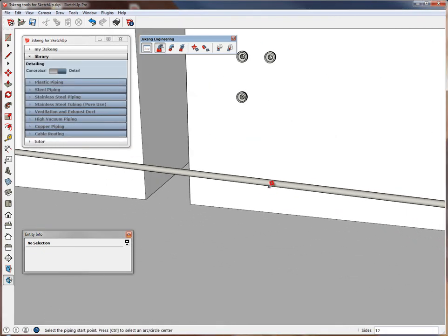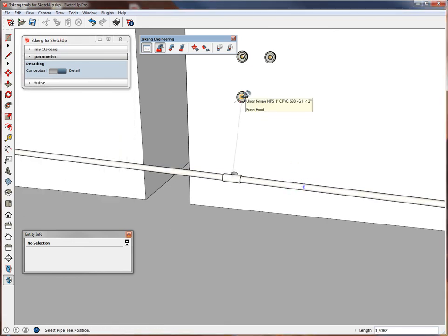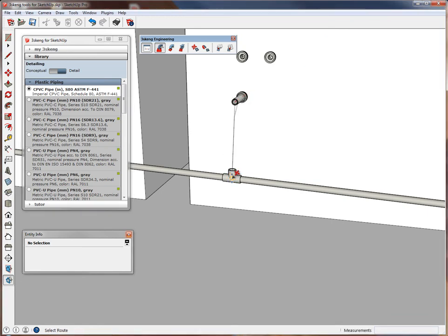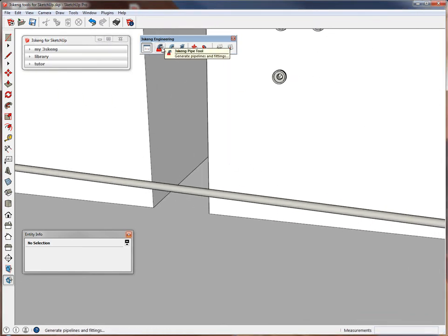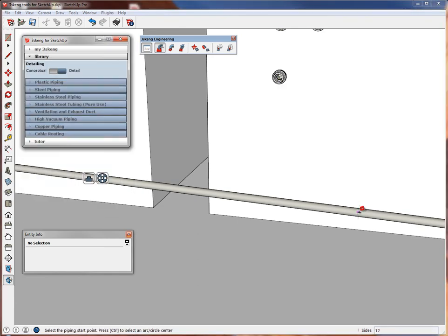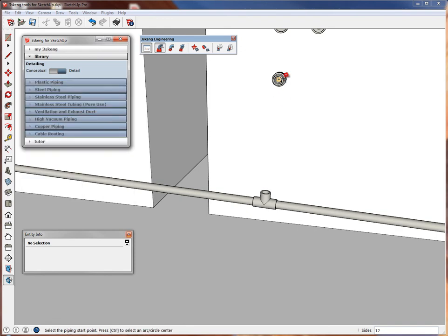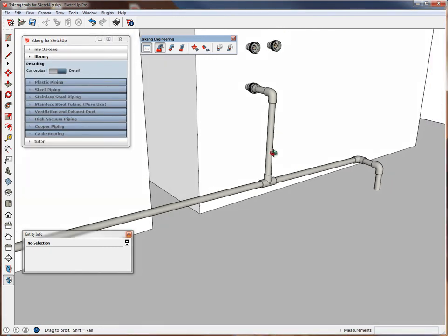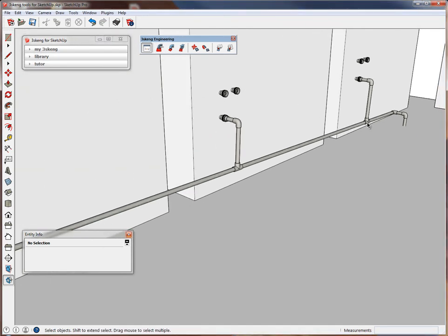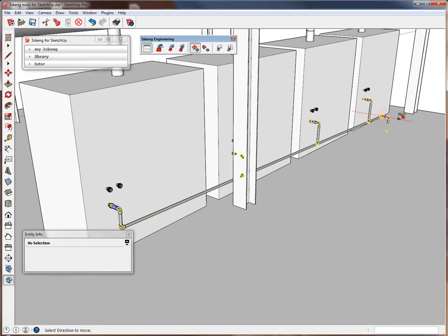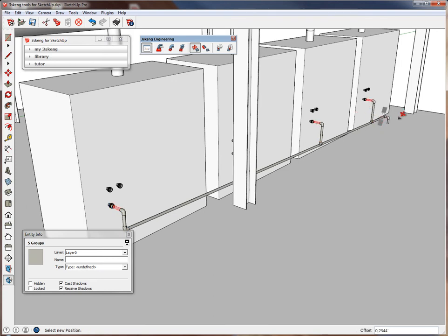We have to do the same for the 2 other connections. First, and the second connection. We can also edit this pipeline based on the free parameters. In this case, we cannot change the slope because the slope is locked due to the angle between T's and elbows. But we can, of course, change it in this axis.